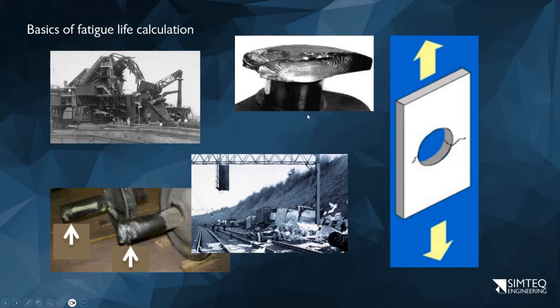Okay, so the basics of fatigue is when we have any kind of structure with repeated loads, at some point we start forming cracks and they grow through the structure. Usually when we talk about fatigue calculations, it's when does the crack start? We're not so much interested in how long it takes to fail, because for high cycle fatigue at least, it tends to be relatively quickly after crack initiation.